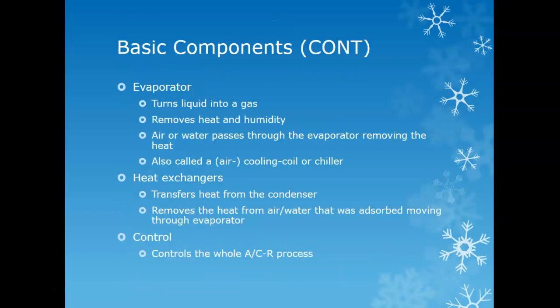So evaporator, this turns liquid into gas. It removes the heat and humidity. Again, something we're grateful for here in the South, because heat and humidity are killers, right? Air or water passes through the evaporator, removing the heat. Okay? You might have also heard it called a chiller.